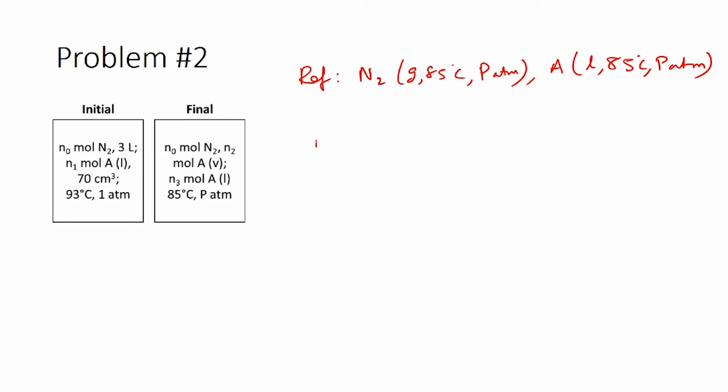The components would be nitrogen, component A as liquid phase and component A as vapor phase. As I had already mentioned, we should always list out components of different phases separately while writing these enthalpy or internal energy tables for phase change operations. In this table you have N initial and U cap initial. Instead of enthalpy we are using internal energy, and you have N final and U cap final, which would be the specific internal energy for the final condition.